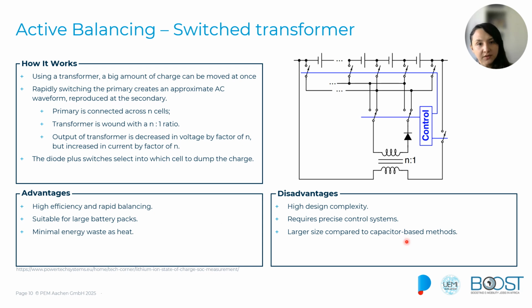The disadvantages of this rely in the complexity, and the implementation of the switched transformer requires advanced control circuitry as well as some power electronics background for making it work correctly. Also, the transformer and the control circuit will increase the overall cost of the BMS, and also I guess it will take more space and more weight of our system to put that transformer there.